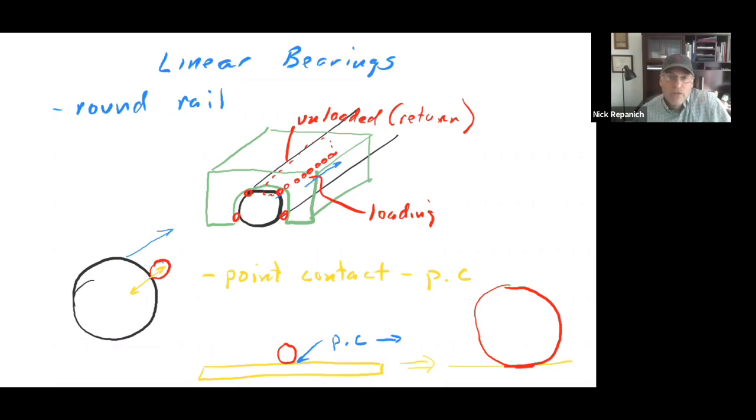It's because there's almost no friction on point contact to point contact until you start to add loading, and then you deform that, and pretty soon you'll start to see little grooves that come, because whenever you deform something and ask it to roll along, there's a period of its rolling when it goes through the flat section that the velocity here is different than the velocity here is different than the velocity here.